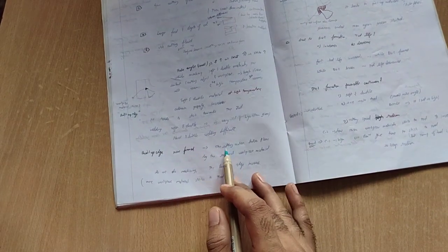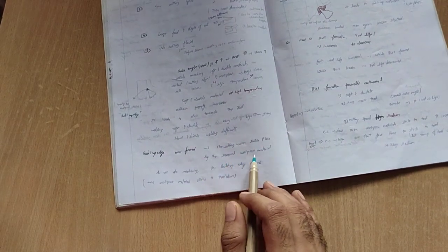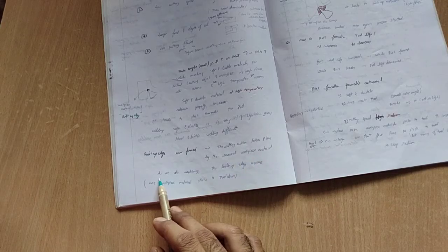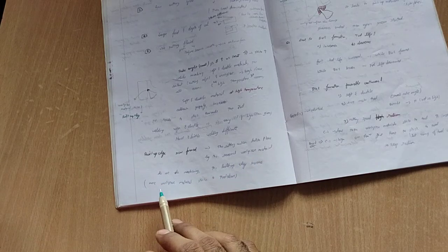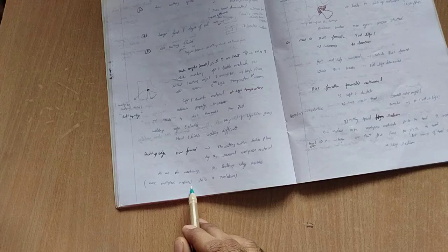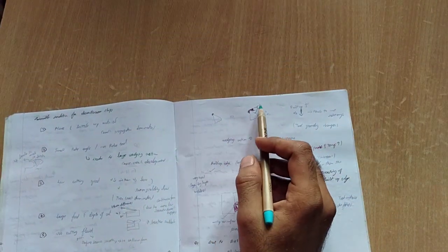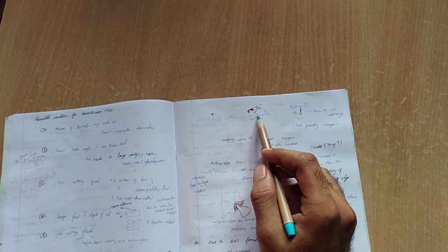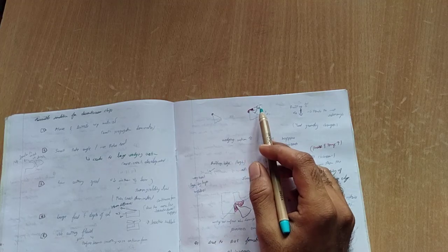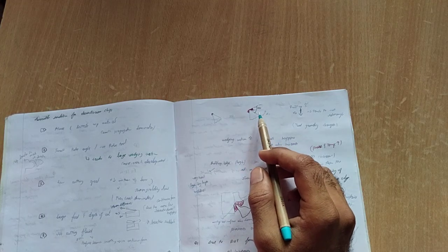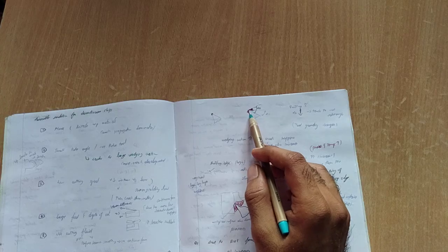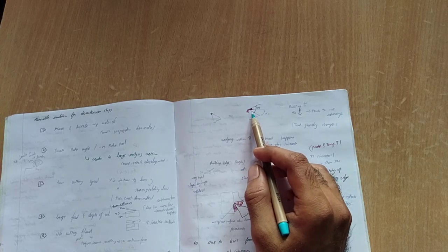When the built-up edge forms, it means the cutting action takes place by covering the workpiece material. As we do machining, the built-up edge increases and more workpiece material sticks to the tool. You can see this is the built-up edge, and as it increases, instead of a positive rake angle, it tends to become a negative rake angle. During a negative rake angle, the stress concentration at the tip is much higher, and it fails very easily.